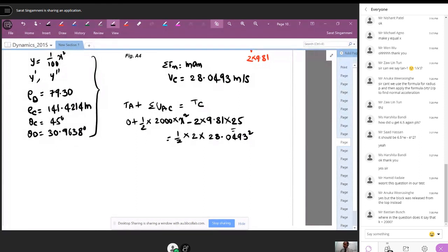Yep, that is the final kinetic energy. So from this, we can calculate x, which is 1.1302 meters. This is the compression that you need. That K of 2000, I forgot to give in the problem during that year, and I was going around the exam halls announcing that. It was a typographical error. So it is given, you don't have to worry about it.